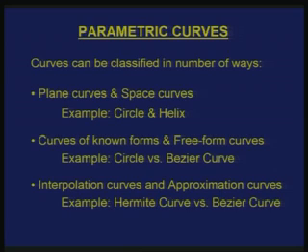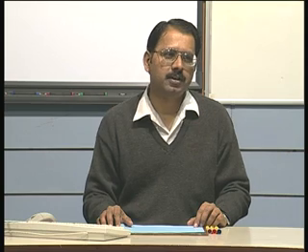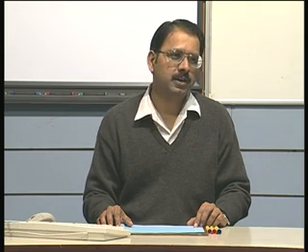For example, I may give, let us say, a set of points and I want a curve which necessarily passes through these points, then I can call it an interpolation curve. Contrary to that, I may have a curve where a set of points are given and these points are used to define the curve. The curve may not necessarily pass through these points, then I can call it an approximation curve.